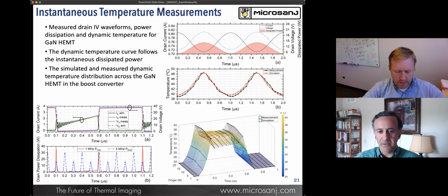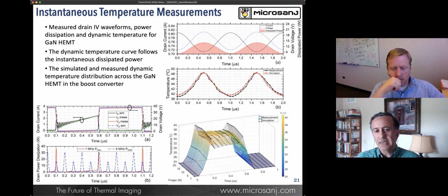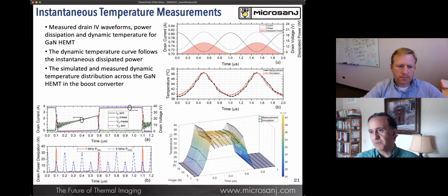And I think, as we push the devices to higher speeds and higher powers, the feature sizes of devices are submicron. So we really need advanced techniques to be able to characterize and calibrate the models. For example, there is a big push on the gallium nitride devices for more advanced substrate or interface layers. And there's always unknowns. When you measure a total thermal resistance, where it's coming from, there could be multiple factors.